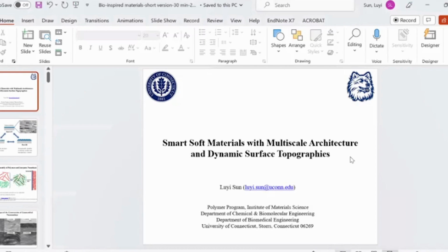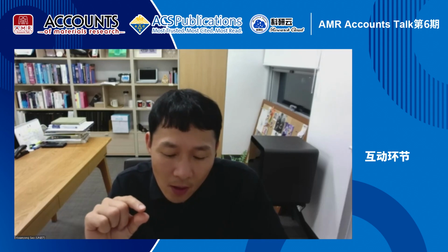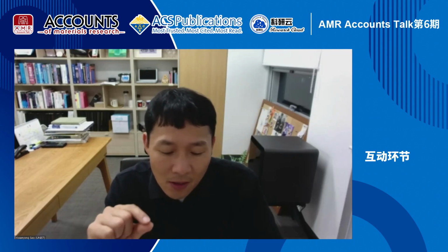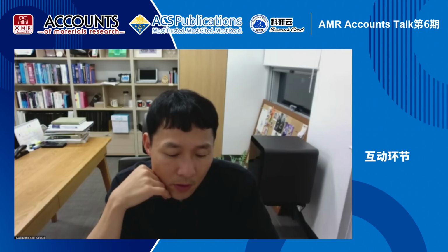Yeah, actually, that's a good question. We can decrease the thickness as thin as possible, but we can consider two things. First thing is the practical fabrication issue. If the substrate is too thin, it's not easy to control during the fabrication process. In our laboratory, we tried up to 10 micron thickness, but so far the reproducible fabrication process required about 20 micron as a minimum thickness.